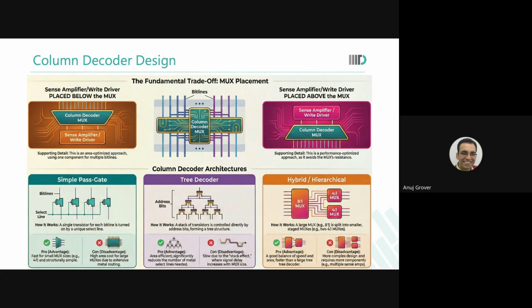In the last class also we talked about the hierarchical multiplexing architecture. We divide the pair of bit lines into two groups. Like if there are 8 pairs of bit lines, we split into 4 and 4 pairs. So I asked you when do we need two sense amplifiers? There you said no, we need one only. So if we are using two muxes and both have one output, how are we needing just one sense amplifier there? So it depends, Arpit.